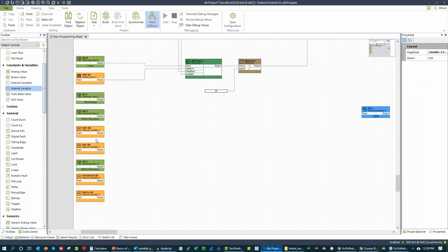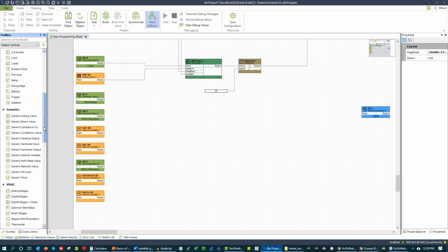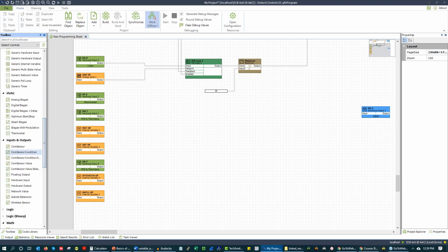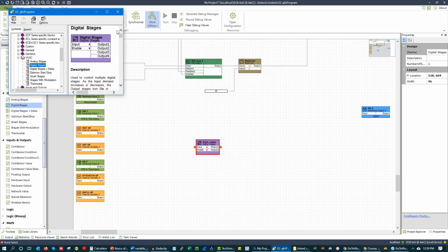All right. So I've got mixed air temp and, all right, the controller will measure mixed air temp and stage the preheating to maintain its set point, 5 degrees adjustable. Now here's where things get a little weird, right? So we have this startup and we actually have this PID loop. And there's a couple different ways we can do this, right? We can do a digital stage, right? So a digital stage is going to, let me show you.